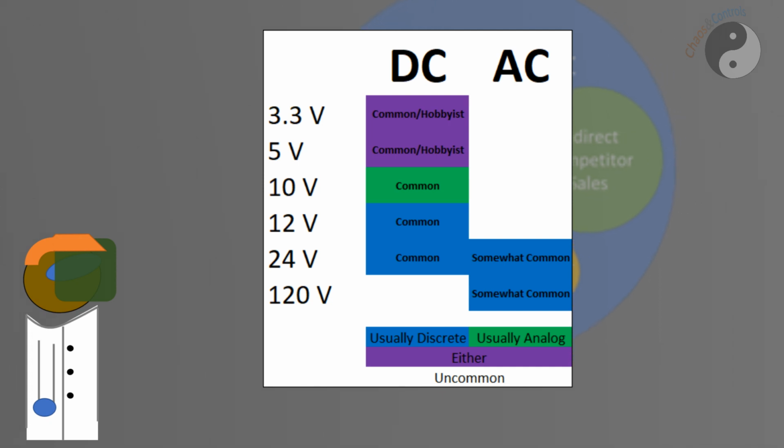On the analog side, things get even more interesting, where we can have a voltage detection, and that can be 0 to 24 volt, or much more commonly a 0 to 10 volt for your analog. And so on a temperature sensor, you might have 0 volts mapped to maybe 0 degrees Fahrenheit, and 10 volts mapped to 150 degrees Fahrenheit, and it's a linear progression in between.